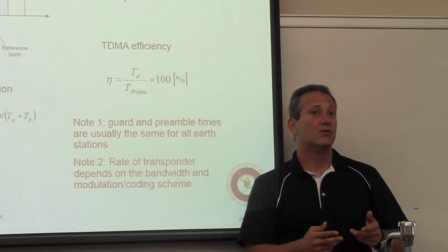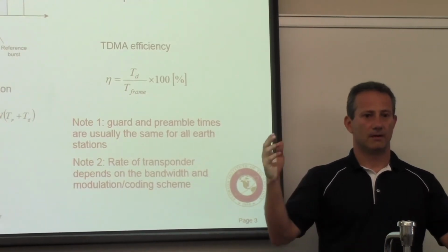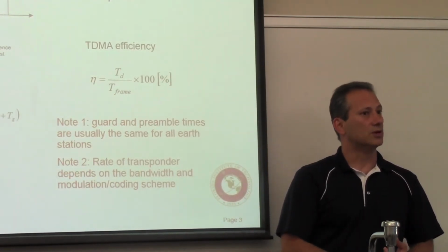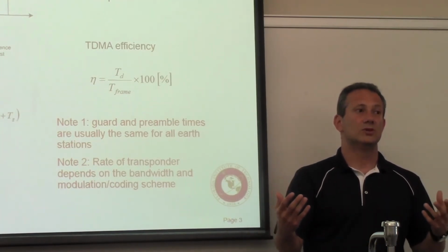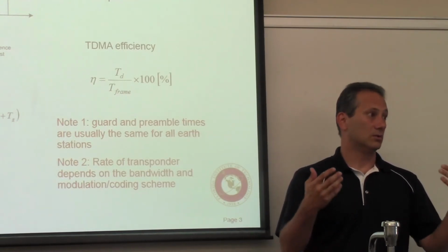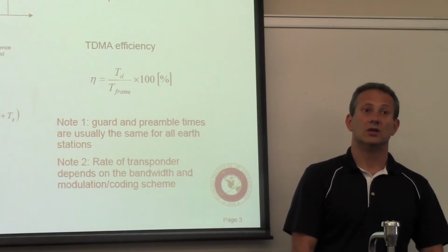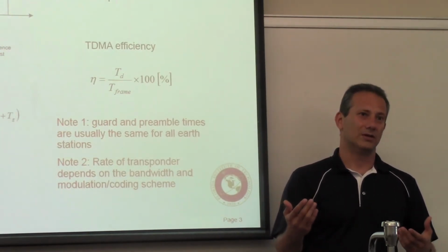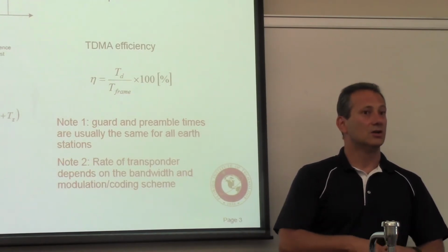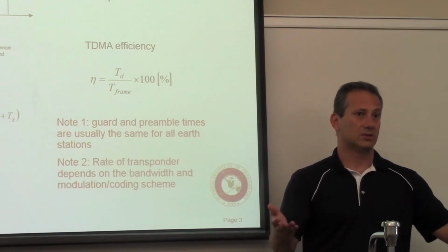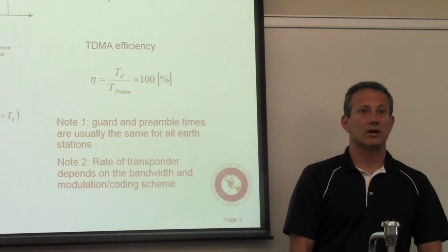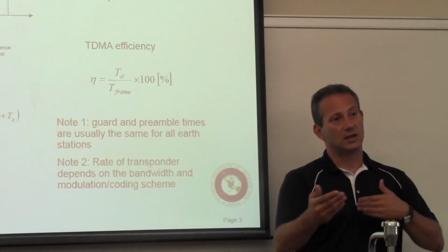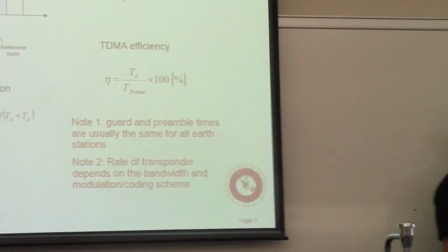So we have a very good efficiency for two reasons. First, we are talking big earth stations with lots of power, so the link margins are good. You're always communicating with a good signal-to-noise ratio, and therefore, you don't have to use very sophisticated coding. You don't have to use turbo codes or convolutional codes that we use in terrestrial networks. The second reason is the channel is much better. We don't have Rayleigh fading to deal with here. Your channel is very much like AWGN, so once you're operating at a sufficient signal-to-noise ratio, you don't have to do much coding and you don't have much of an overhead. So the only overhead is what you have for synchronization and the signaling overhead that makes the earth station function and improve.